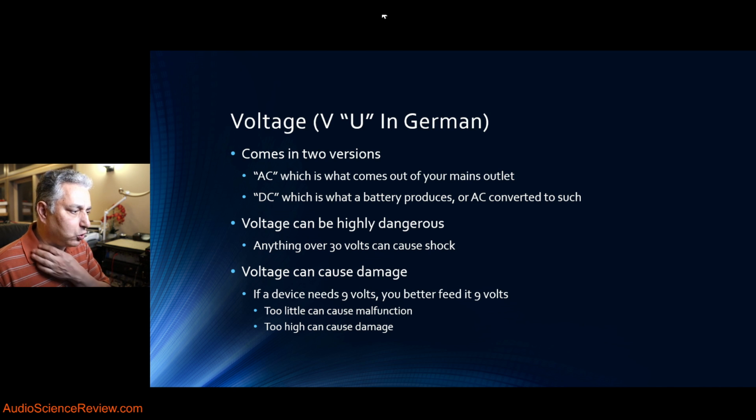If you have too low of a voltage, you can't damage the device, but it may not turn on, and it may turn on and act flaky. It may get stuck in an infinite loop where it tries to turn on and turns off. So again, best to stick with whatever voltage that you need to have for the device to operate that the designer assumed.